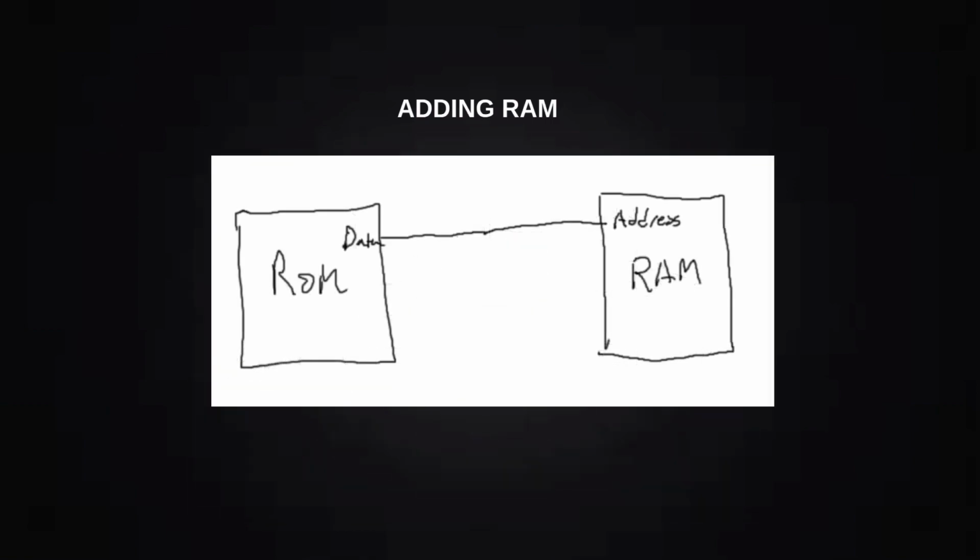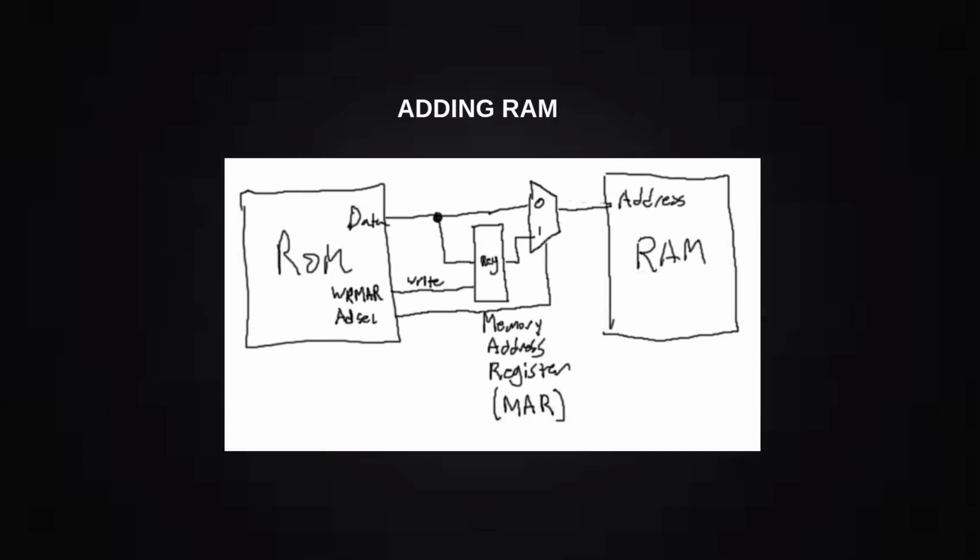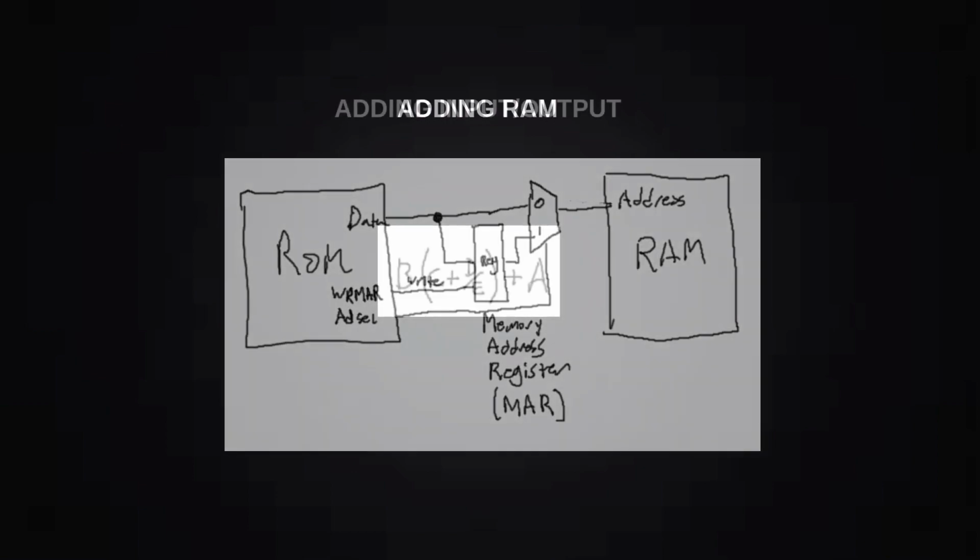Of course, providing an address directly is one option, but another option is to have a register provide the address itself. In this sort of configuration, this register is referred to as a pointer register because it points to a specific location in memory. This sort of configuration seems useless at first. After all, it requires more control lines from your ROM, and accessing memory would take two operations if it's done this way, one for loading the address into the pointer register, and one for accessing memory. But saving the address in the register can be advantageous if you have to use that address repeatedly. There's also other uses when it comes to loops, but we'll be covering that later.